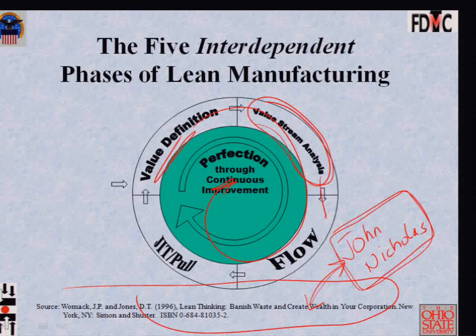Having identified the value streams, you undertake to do layout changes, material handling changes, you institute visual control, you look at poka-yoke, you look at water striders. Essentially, you look at the layout design, everything that has to do with the physical flow of the product. Try to eliminate all wastes and delays in the physical flow of product inside the value stream. That is step number 3.